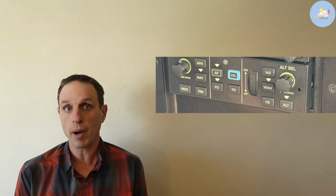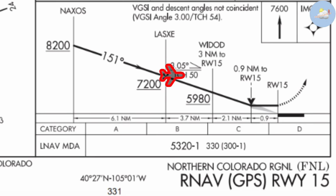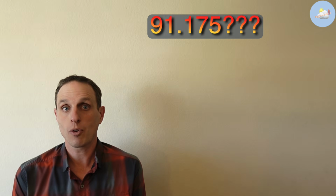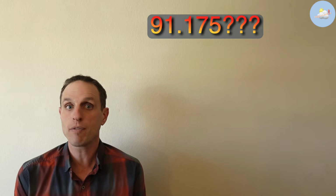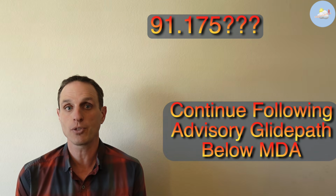So this means that when you are using an autopilot to follow an advisory glide path or a +V, you must manually monitor your altitude relative to the minimum descent altitude. And upon reaching the minimum descent altitude, you have a couple options. If you are able to comply with all the requirements of 91.175, you can continue following the advisory glide path